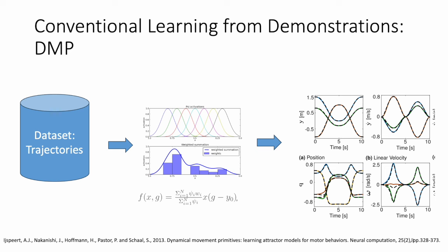This basis function can span the entire space for the input. And then you have the parameters which define the goal position. By that, you can provide this equation with a new goal point, where the system can generalize this demonstration to different start and goal points based on a single demonstration. So you see that this is nice. You can generalize a demonstration of grabbing a coffee mug to different coffee mug locations.